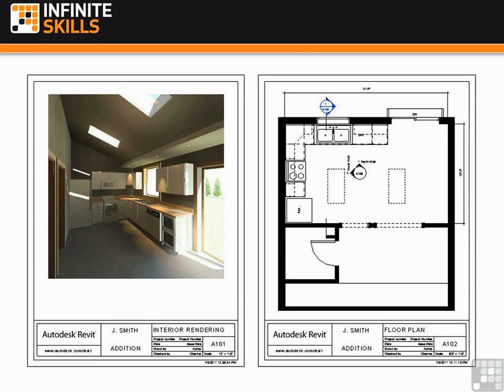There's a kitchen. We're also going to be creating a floor plan, which will have blacked out walls. This is really a set of drawings that is intended for the client to review and look and see what this design is going to be all about. So there is a set of floor plans, which is blacked out walls. We'll show you how to do that. And also you can see right here, these are the skylights above, and those are the actual skylights. Those aren't just lines. If the skylight moved, those would move as well. Everything in here is going to be live like that.